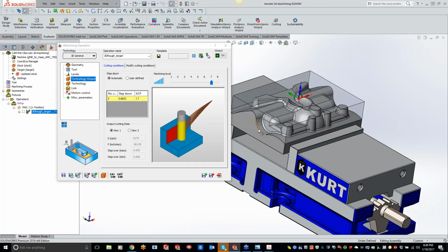So, and again, that's the power of iMachining. You can do a roughing toolpath and then just do a finish right over the top of it because, again, we can control all of that scallop data, and it saves you just tons in not only programming time, but cycle time, because you don't have to do a semi-rough, or I'm sorry, a semi-finish pass. Well, and then also when you're roughing it out, you're not really air cutting anymore. Exactly, keeping that scallop height the same.